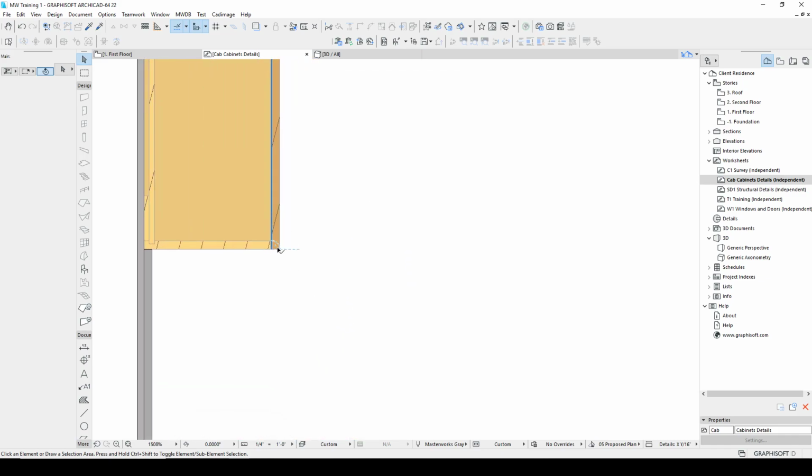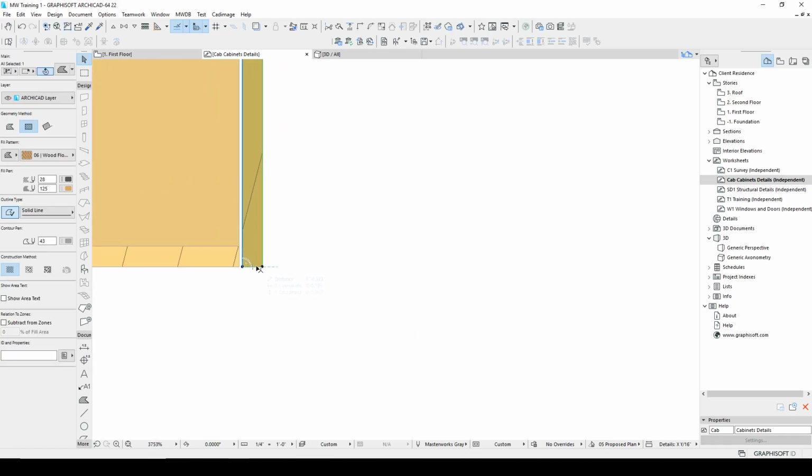I just noticed here, oh, I really want a light rail, so I'm going to bring this down 2 inches. I'm going to put a piece in here. Copy the properties with Alt. So I copy those properties with Alt. And then the next thing I draw keeps going. So I'm going to do an Alt Y, which will lock in my Y value.